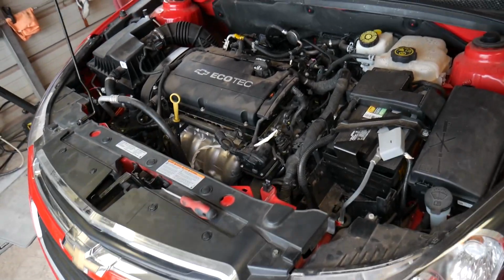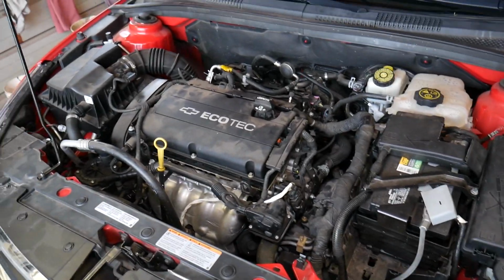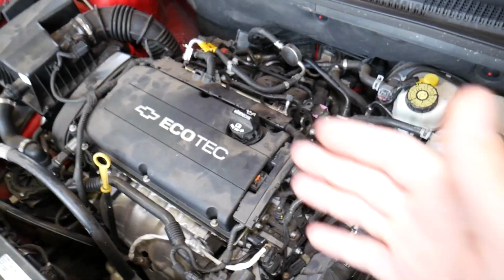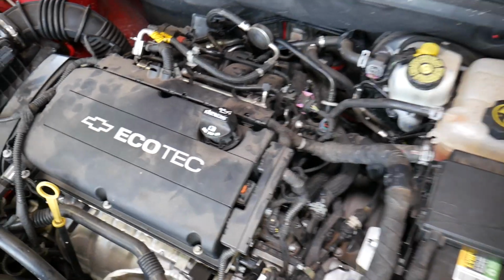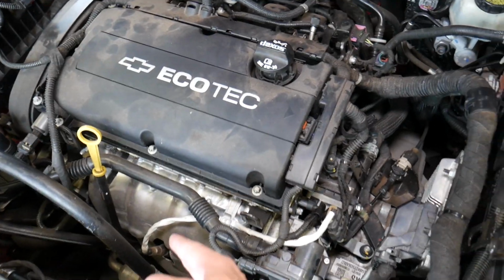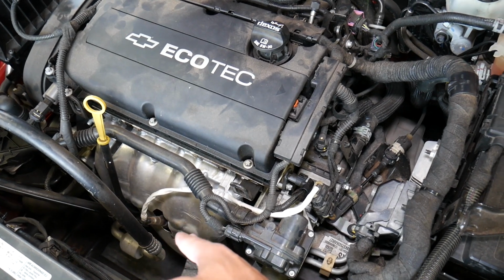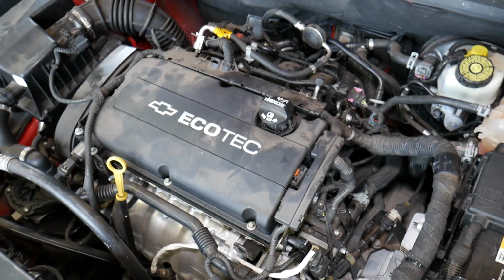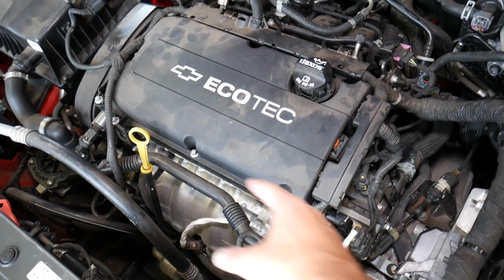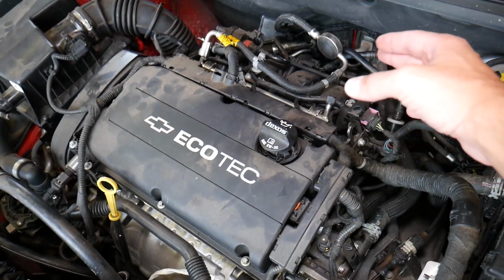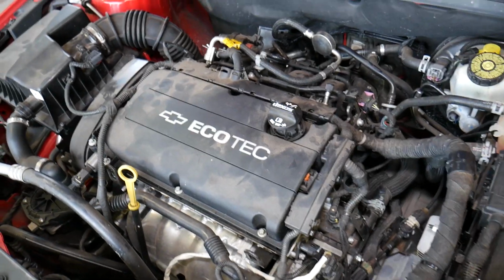Since it says camshaft position sensor B, now we're going to explain what that means. Doesn't matter which engine you have, you need to locate your intake manifold, where the car gets its air and fuel from, and the exhaust, where everything comes out of the engine. Now what does camshaft position sensor B mean? B stands for the camshaft on the exhaust side, for the exhaust valves. If it's A, it's on the intake. It's always like that. Why?